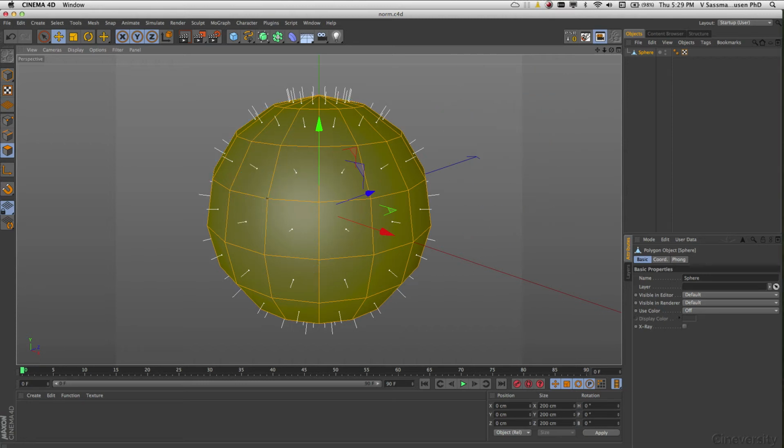Displacement mapping means that we take the points of this object and we move these points up and down. And up and down means, of course, relative to this direction. And the idea is similar to the bump map, but has a completely different result. Because when we move this point up and down, for example, the contour, the outline, would change dramatically. And I take green here purposely because I want to show something else.